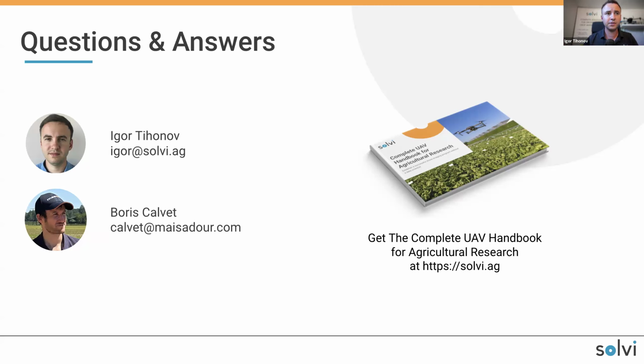And then RTK is obviously very important. If you want to subtract the data from one elevation map to another, it has to have high accuracy. But I'm sure the RTK technology on the drones will improve over time and the measurements will get more accurate.